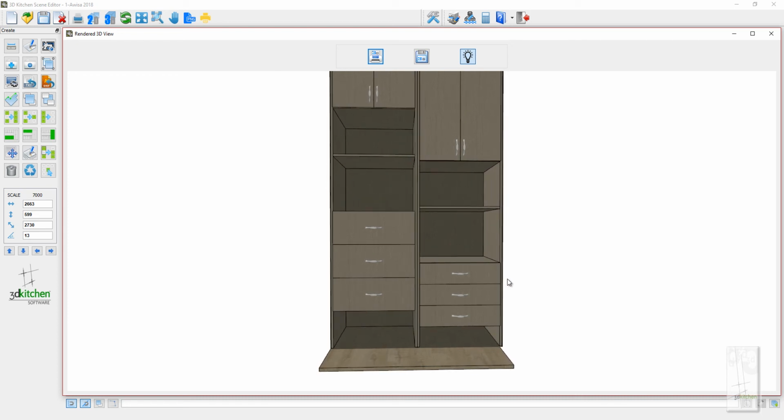Now the importance of that is especially in the 3D design, you can line your shelving up or drawers up quite simply. But the big benefit is for CNC operators, because the shelving, all the positions for your drilling are automatically generated, whether they're fixed shelving or adjustable shelving. The drawer heights, the runners, the hinges for the doors, and everything is all automatic.